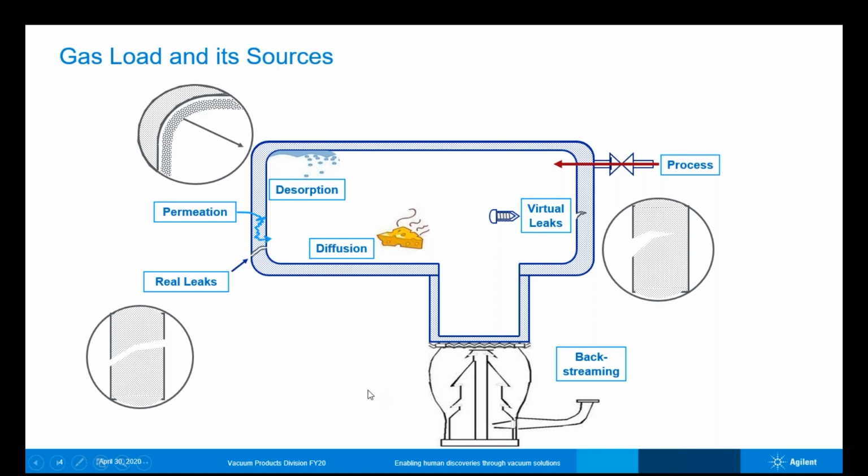When we think about the industrial world though, permeation, that the graphic that just disappeared, that really shows up really at much lower pressures than are typical for industrial processes, something around 10 to the minus 8, 10 to the minus 9, where we're starting to be concerned about whether we have O-rings that have some permeability for helium, for example, or the permeability of our vacuum chamber and its ability to emit hydrogen. Those are typical problems that show up at much lower pressures. So we can kind of get rid of that.